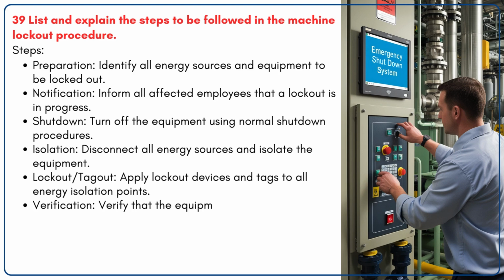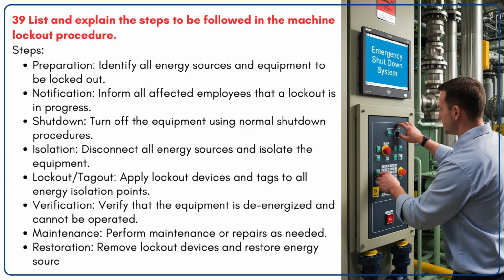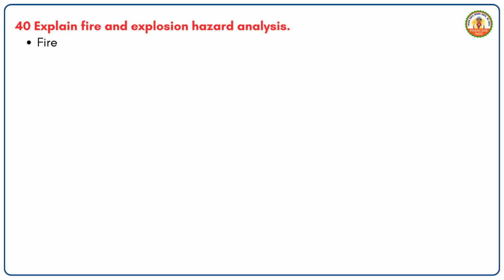Verification. Verify that the equipment is de-energized and cannot be operated. Maintenance. Perform maintenance or repairs as needed. Restoration. Remove lockout devices and restore energy sources, then test the equipment. 40. Explain fire and explosion hazard analysis.